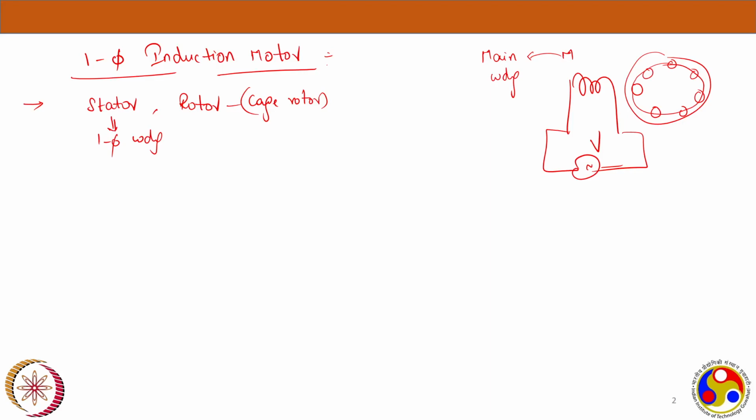Will the motor run? Will current pass through the rotor, because that's what the rotating magnetic field is. Whenever you pass an alternating current through a winding, flux will be induced, and EMF will be induced, and the flux will be time varying, so that you get a rotating magnetic field. We saw those concepts before. Now, will the same happen here? Will the motor run, or will rotor current pass? That's the question.